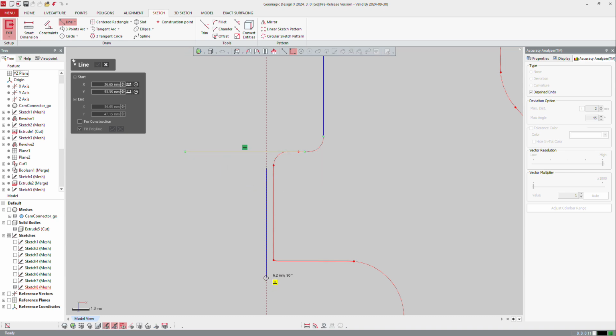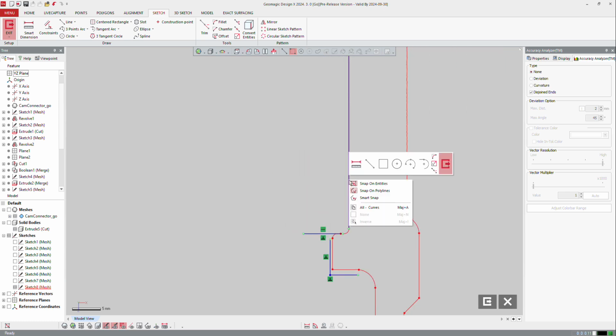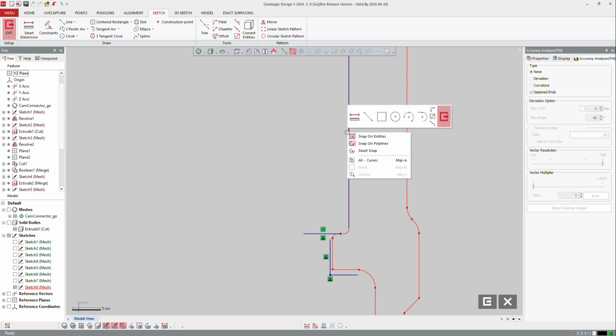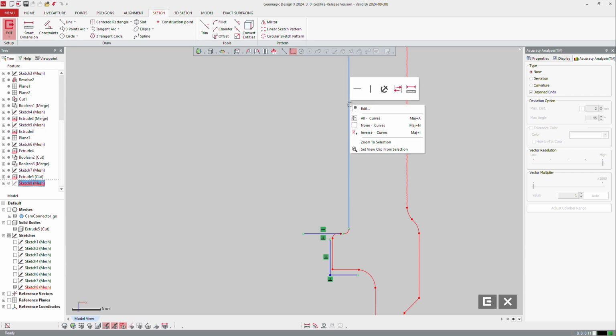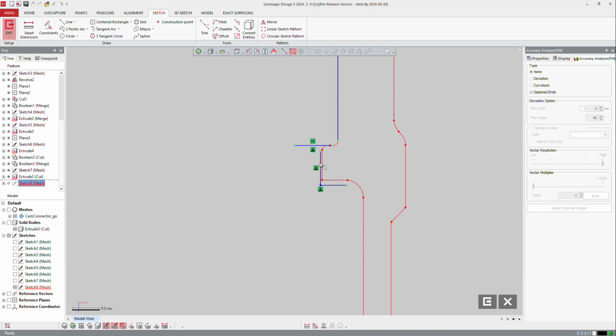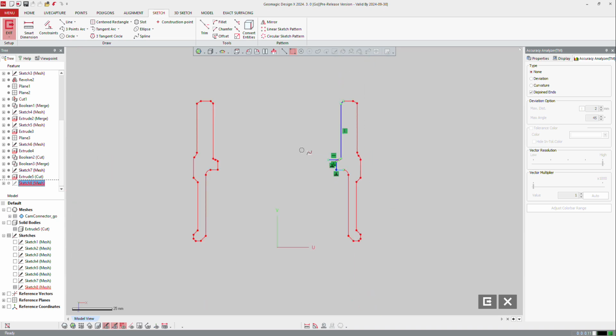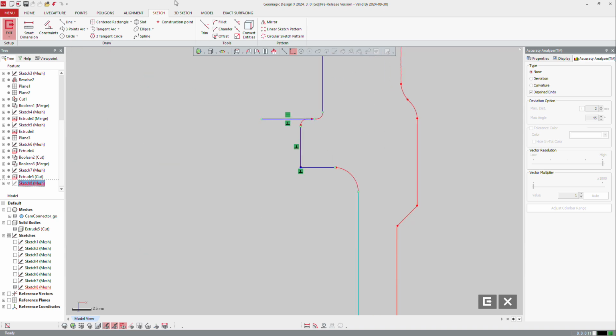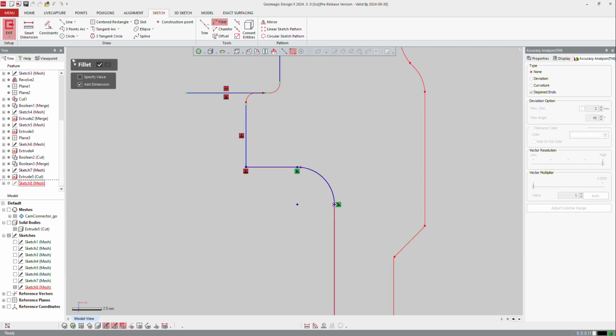And again, you can create by double clicking or by just clicking like that, you define horizontality and verticality. Otherwise, you have to do it afterwards, like right mouse click on the line and verticality. This one got an angle. And if you do it for outside, you need to re-magnet the curve. Let's finish that with that curve and that curve. Again, that one will be vertical. And between those two, I will create a fillet, ask the software to add a dimension on that, and create a fillet here to there and be sure that you get the right one, and modify 315.